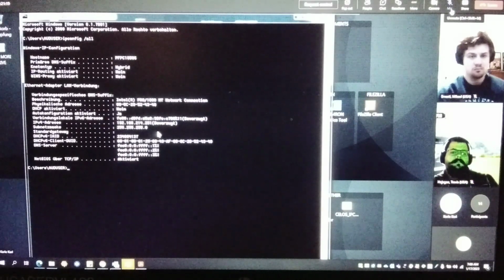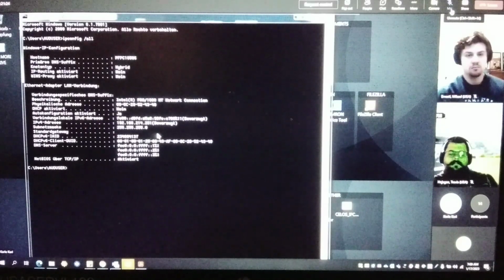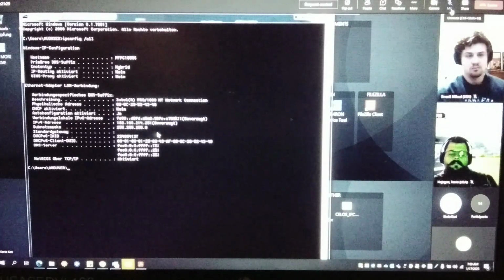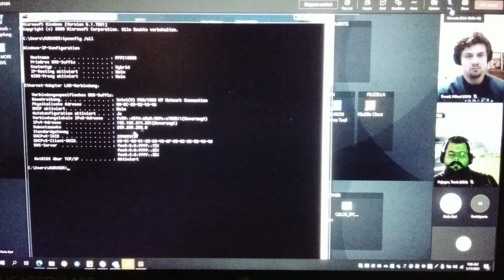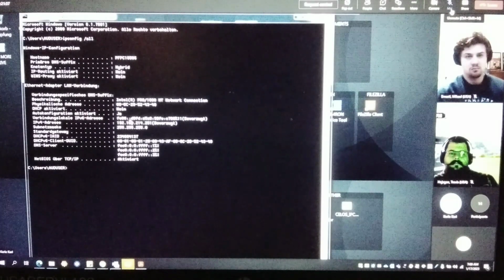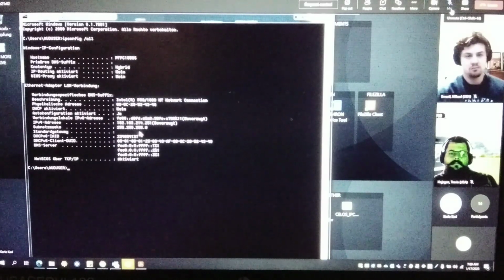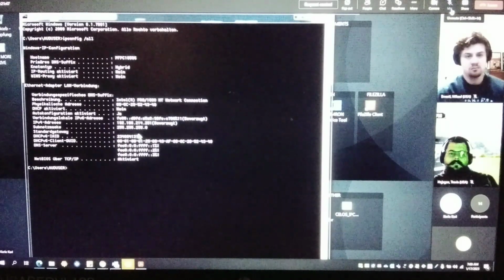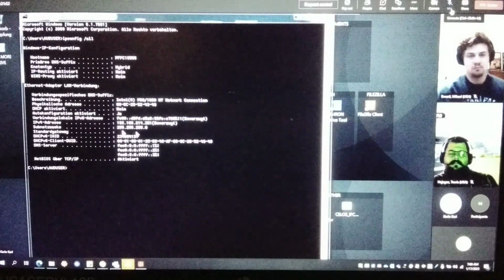And so what must be true? If you would like to be connected to one of the numeric controller units, it must be true that your laptop is configured to the same network range. So the adjustments here in the first 3 blocks of values belonging to the IP and to the subnet mask range must be completely identical to the configuration of every machine controller unit. So that means now you belong to the same network range.